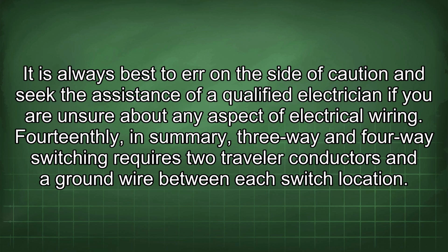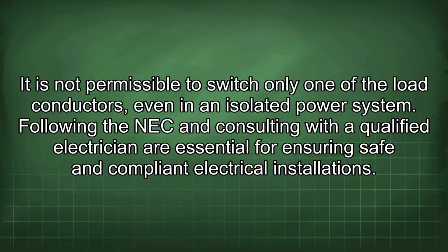14thly, in summary, 3-way and 4-way switching requires 2 traveler conductors and a ground wire between each switch location. It is not permissible to switch only one of the load conductors, even in an isolated power system. Following the NEC and consulting with a qualified electrician are essential for ensuring safe and compliant electrical installation.